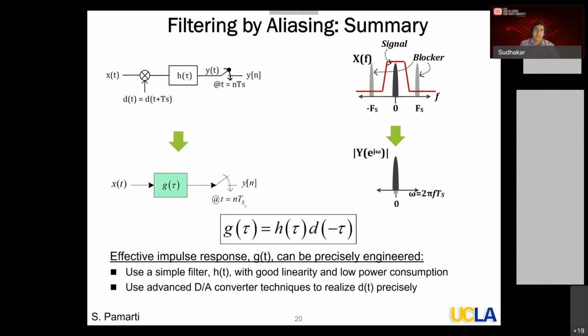Otherwise, the filter operation is going to get disturbed. So it is fundamentally a periodically time varying circuit, but as far as the samples are concerned, it is acting like a linear time invariant system. That's what I'm showing you in the bottom left, right? So that is where the relation is coming from. Okay, that's where the constraint is coming from.